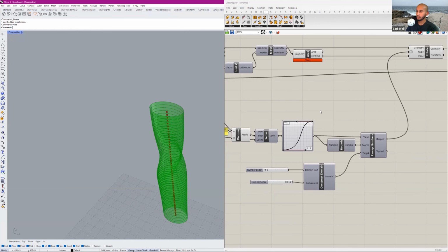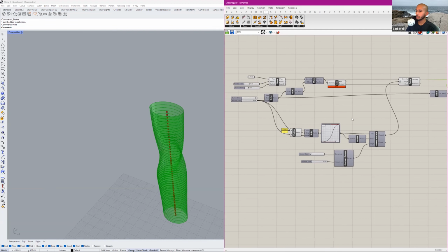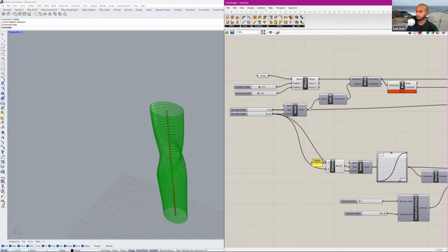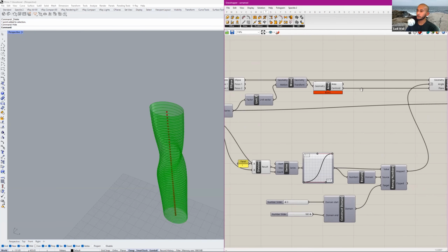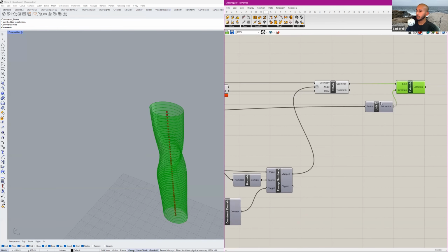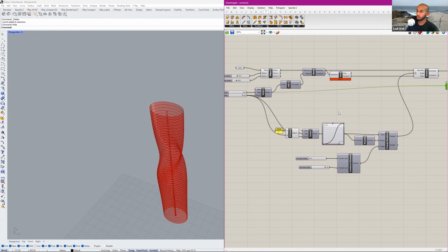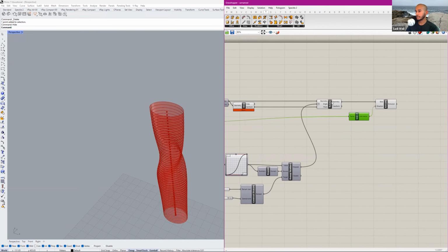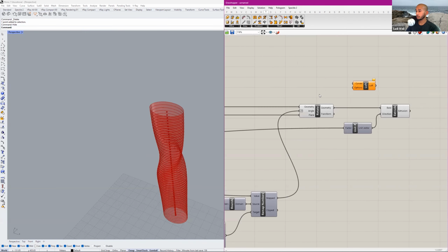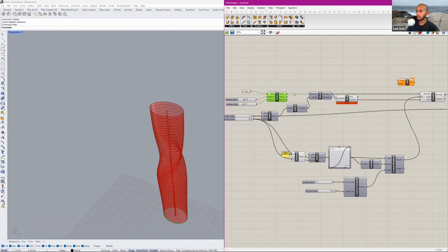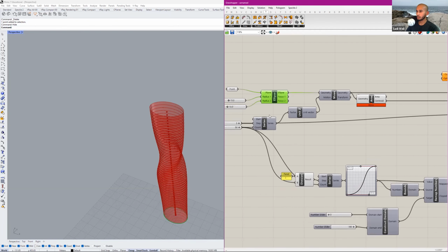And before I do that, I'll go over one more thing about Grasshopper, which is that you can connect multiple wires into the same input. There really wasn't any use case here for us to do that. But for example, if you were to loft, which is another component and a command between geometries, let's say we had,